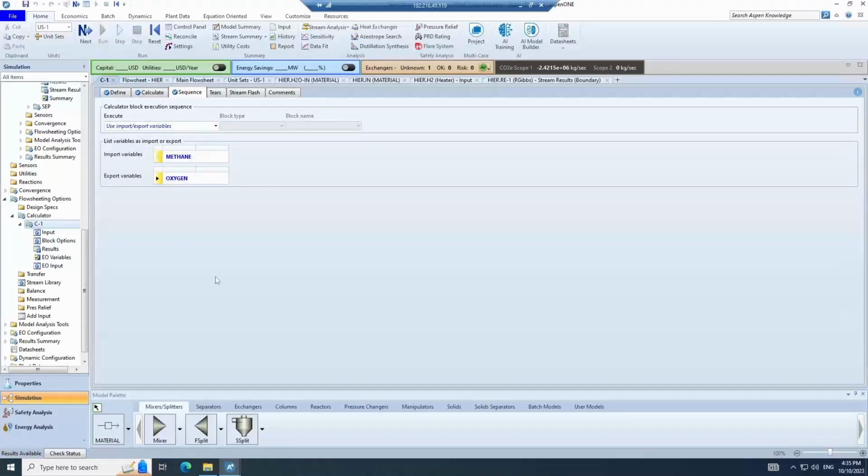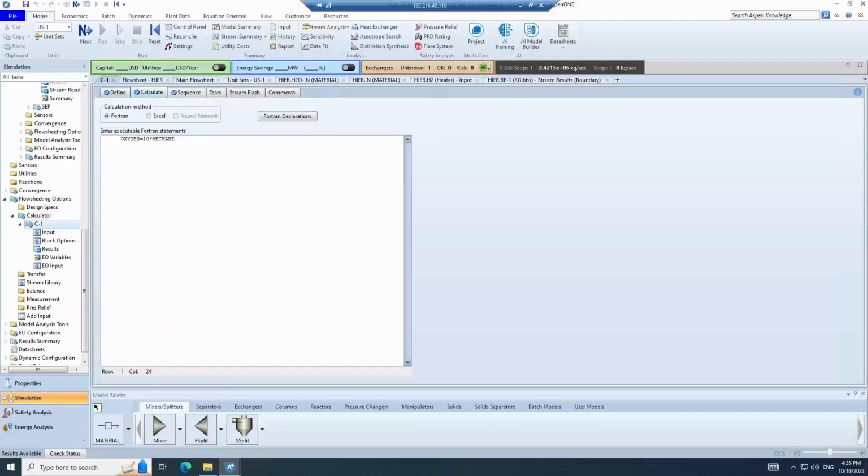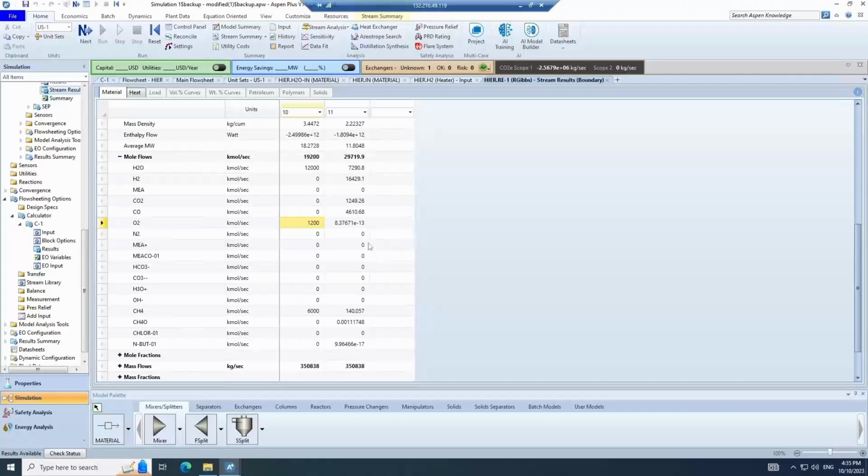And if we run it, we can also recall that previously our oxygen was at 200. And if we return to our reactor, we can now see that our oxygen is actually at 10 times what the methane was here. And this does affect how things are being reacted. Oxygen is no longer being limited. And we can very easily go in and just switch it out here. Let's say we want it to be 0.2 in order to limit oxygen more. Run this once more and returning here, now we have hydrogen once again being produced, and our oxygen is much lower in this case here.